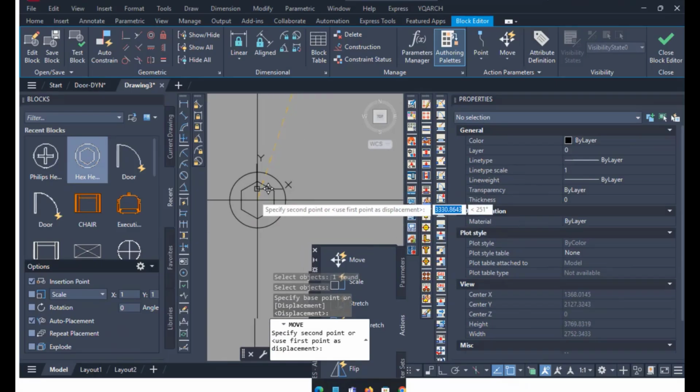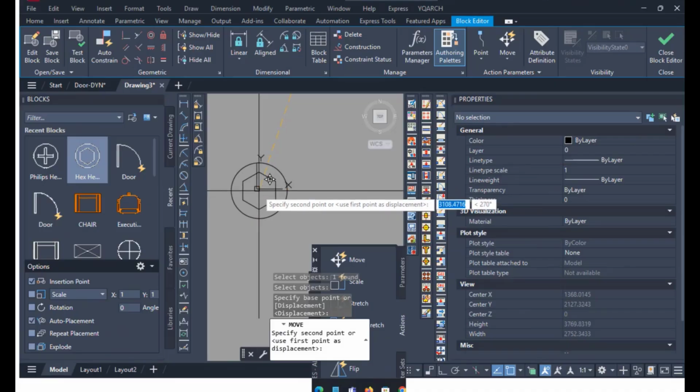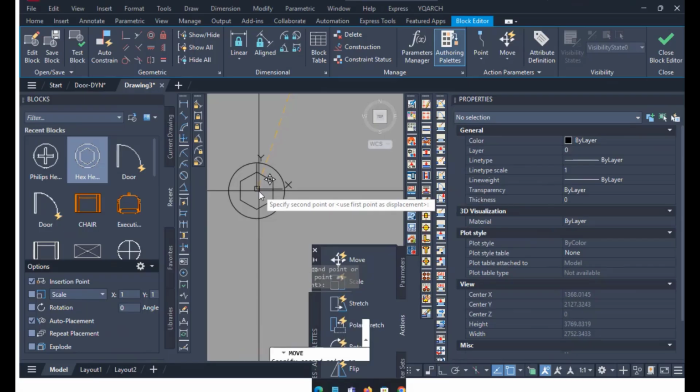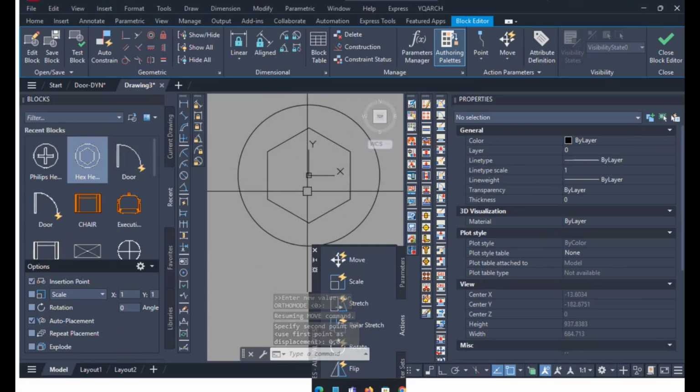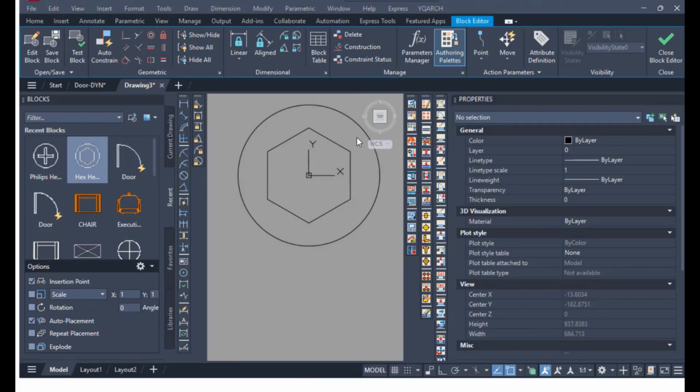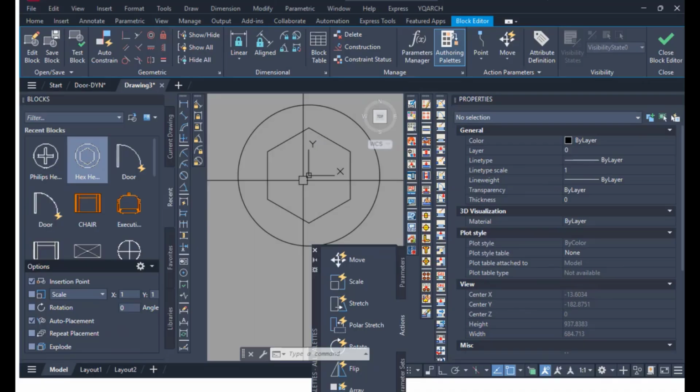To the location here, we have a trick for you. It's the sharp symbol, #0, command 0. Moving to the position of 0,0, because you don't have the reference, right? This one, you have to use the sharp symbol in order to tell AutoCAD to use the absolute coordinate.